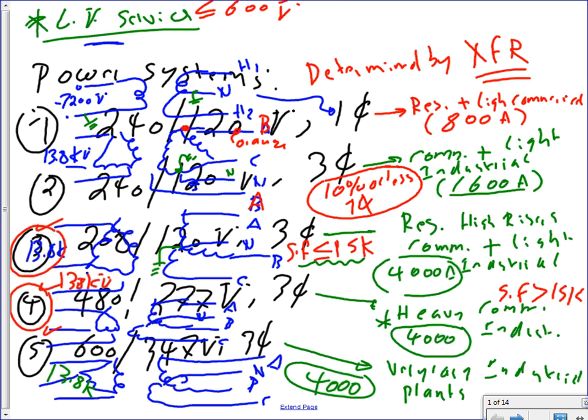99% of the time. There's another primary that they use if you guys want to throw it. The utility is moving away from it. It's called 4160, 4.16 kV. That's another common voltage that they use. A lot of utilities are moving away from it because it's lower voltage in their mind. So 13.8 is typically what you're going to be encountering.